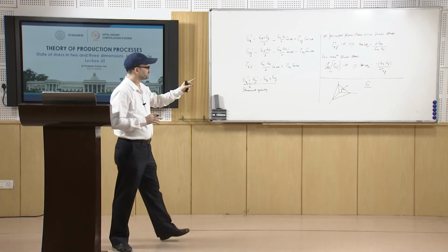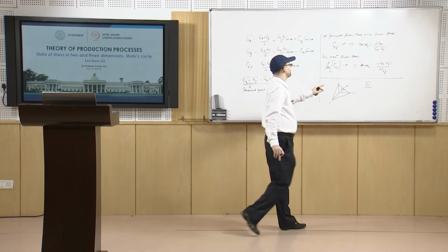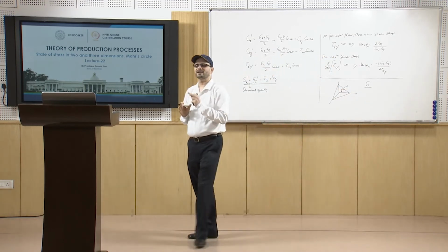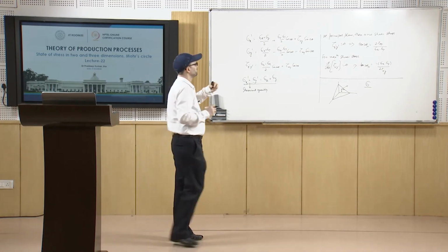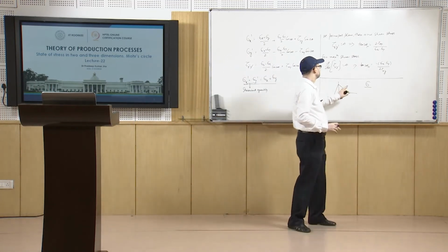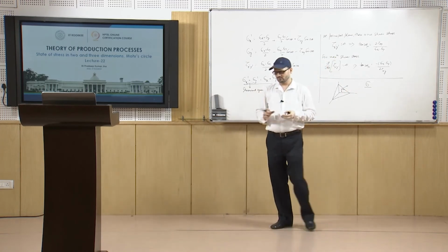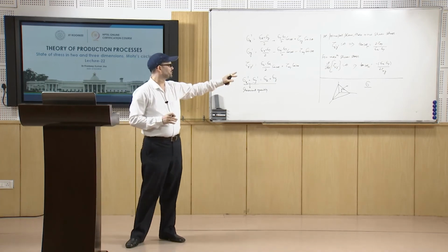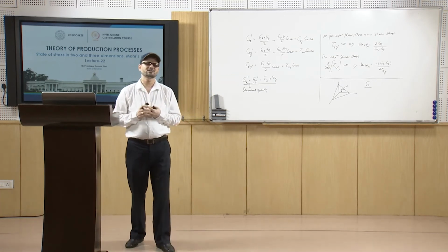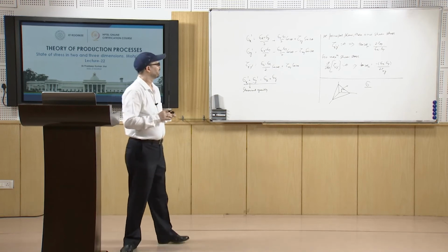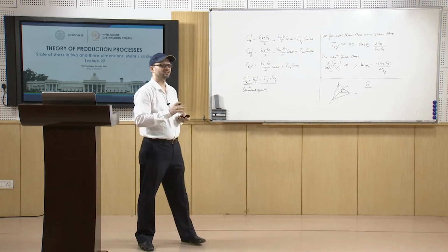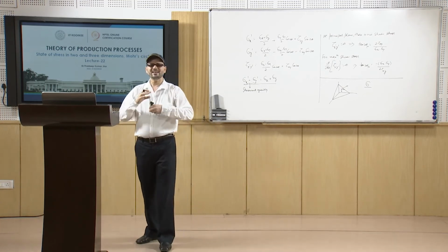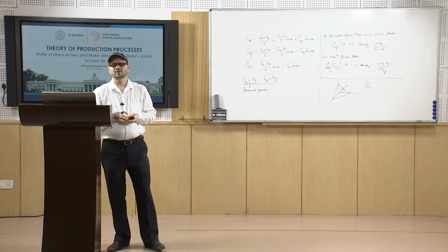analysis, and for this principal stress, let l, m and n be the direction cosines, meaning cos theta, that is the angles with the x, y and z axes. So, if l, m and n are the direction cosines of these 3 directions, you can have the 3 equations by summation of forces, and the 3 equations lead to equations like this.